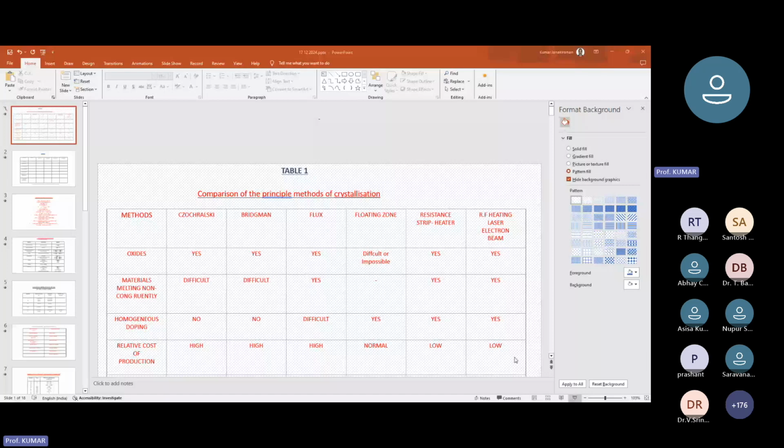So that can be achieved by what is called intrinsic defect control, which is called EL2, energy level 2. In the case of gallium arsenide, arsenic excess will produce this kind of defect levels, called energy level 2 or EL2, and that can itself give rise to electrical resistivity of the order of 10 to the power 7.